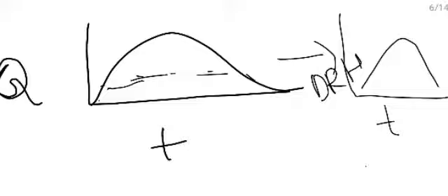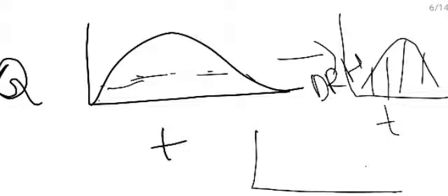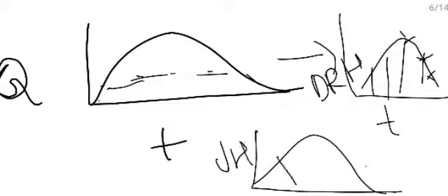So for 1 centimeter occurrence of rainfall, what you have to do, divide all these coordinates by the depth of precipitation. So you will be getting some unit hydrograph. The area of this will give you 1 centimeter. I think you are okay with unit hydrograph. Now it is a characteristic of the basin. We are considering this as a characteristic of basin.